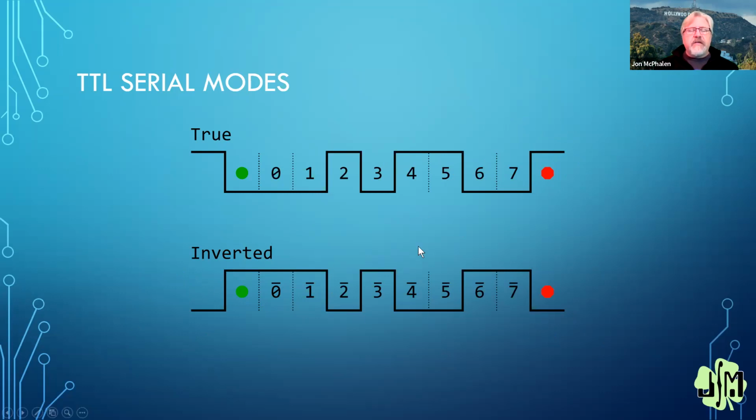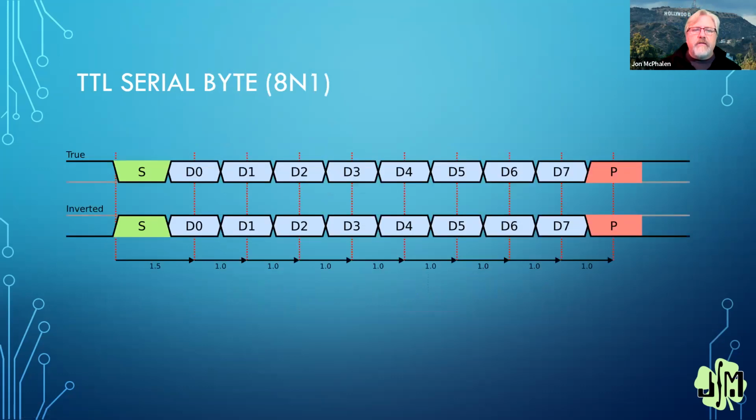Again, if you have this in the P2, it's really easy to deal with because we can tell the pin to invert the signal coming in, and everything from there looks like this. This is another way. Now, if you're coding your own serial stuff, which you don't have to in the P2 anymore with the smart pins, but if you were, what we tend to do is we wait for the start bit, and then we set a timer for 1.5 bit periods.